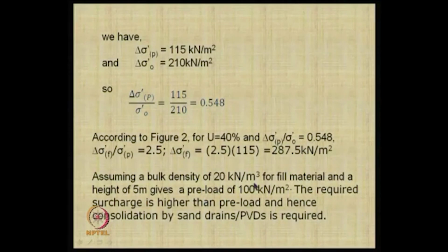So, the preload will be about 100, and if I leave it for 9 months, you have to monitor the settlements also. We expect that the settlements will be sufficient, but normally, you are in a place where everything is clay, and getting a preload is very expensive.